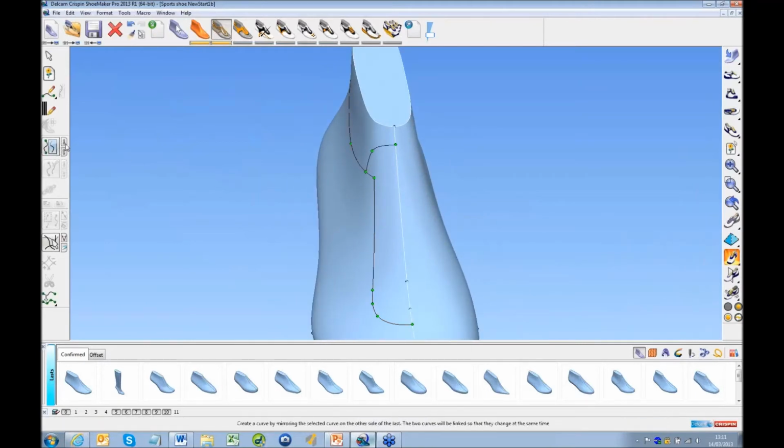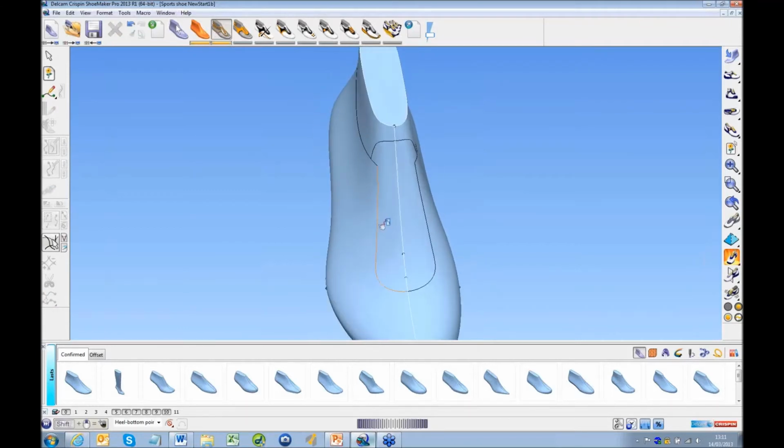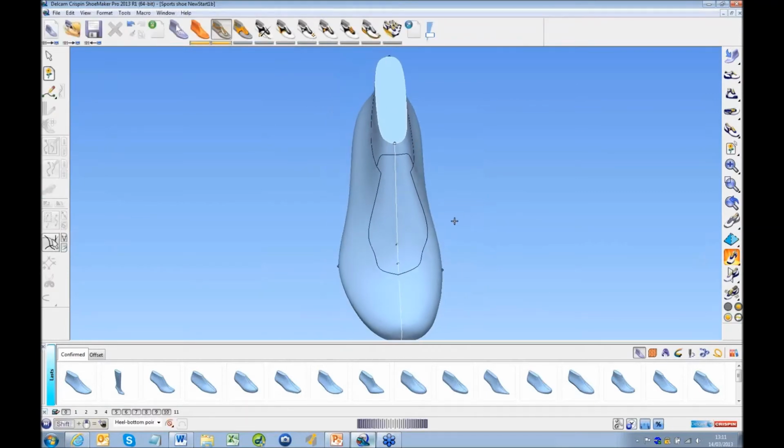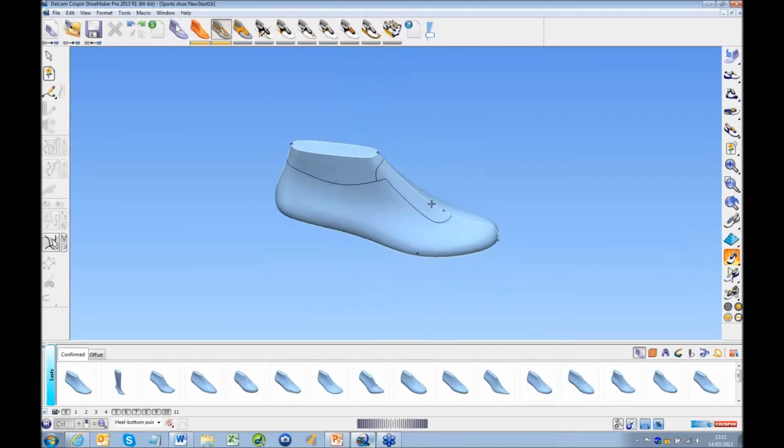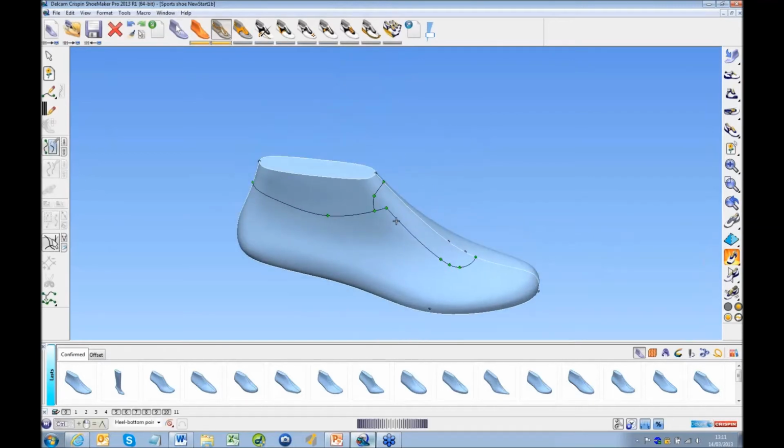So these three star lines, I'm now going to say, do you want to mirror them linked or unlinked? Here, if I say we want linked copies of these star lines, that means when I edit the star lines on one side, the other side will automatically update and the design stays synchronized in two halves. Okay, so we can create and we can edit starline curves.